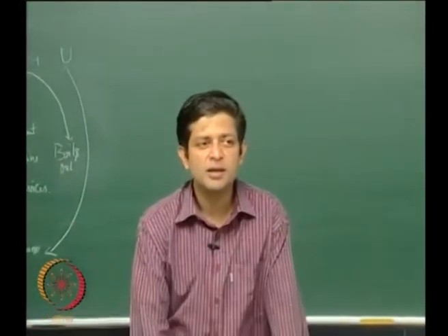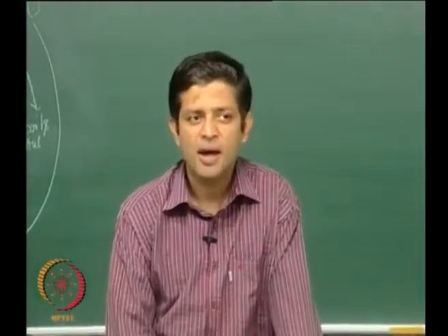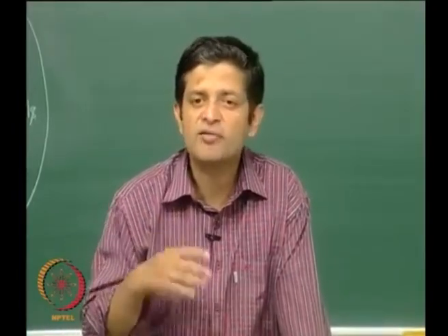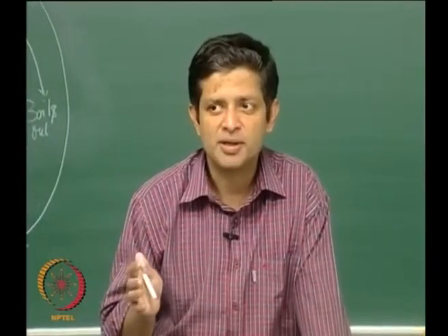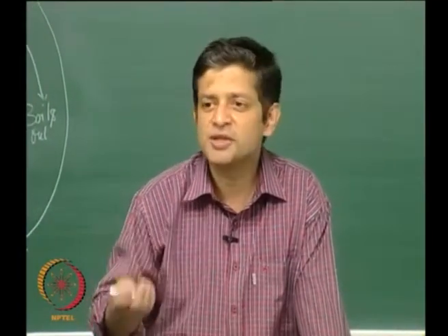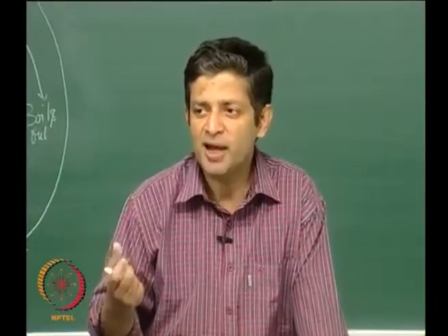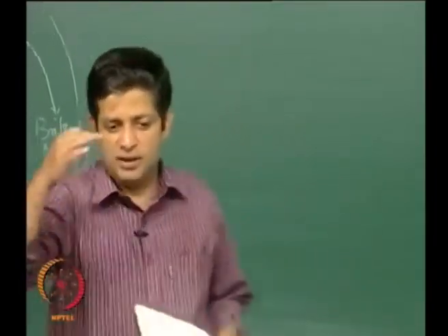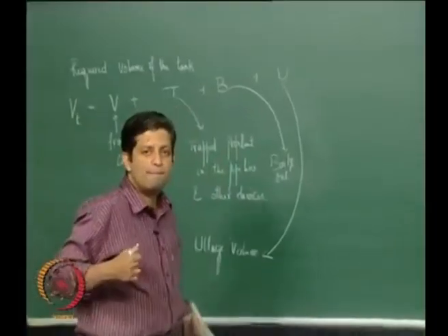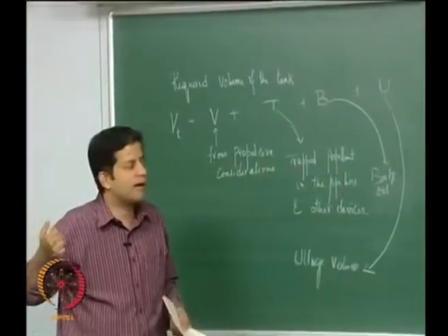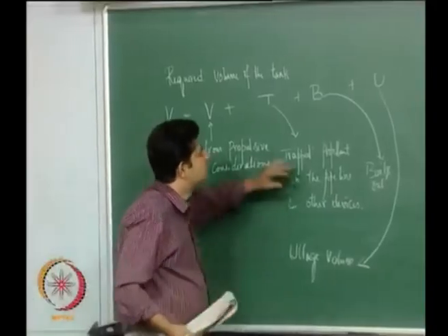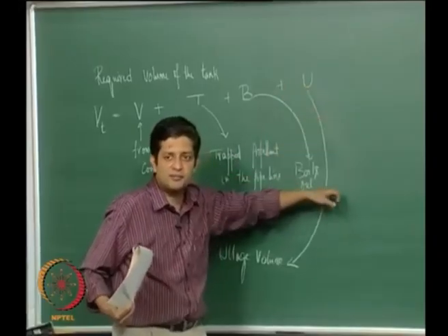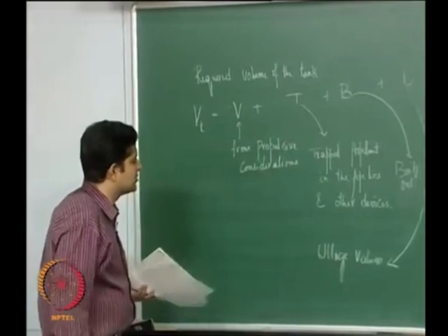If there is boiling, then the pressure tends to build up very rapidly, and the tank may not be designed for a high pressure, particularly if you are looking at a pump fed system, because in a pump fed system, most of the pressurization is given by the pump. So the tank might be able to withstand only a few bar pressure. So if you fill the entire tank with liquid, then as the liquid boils, the pressure will build up, and therefore that might create a problem. So you give it a small extra space so that the pressure can also act, right. So this is known as ullage volume.